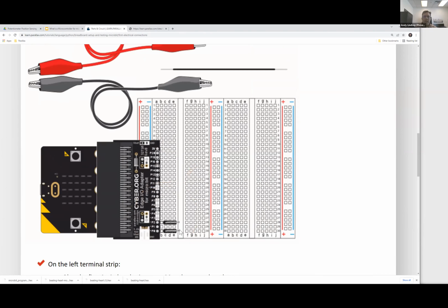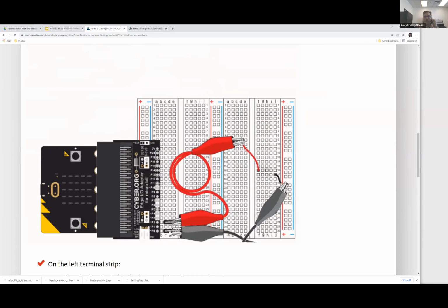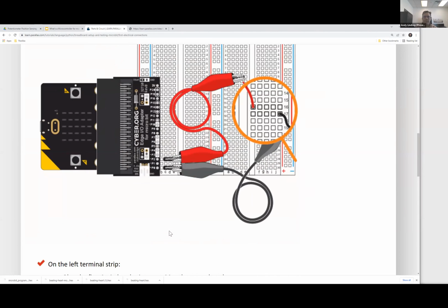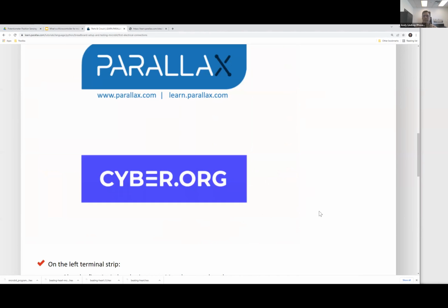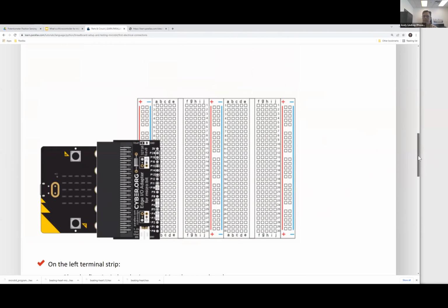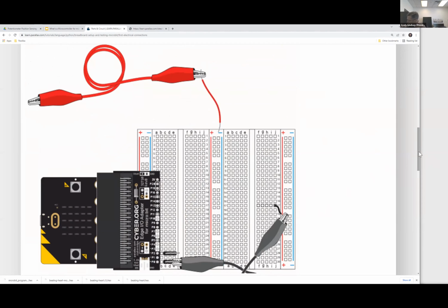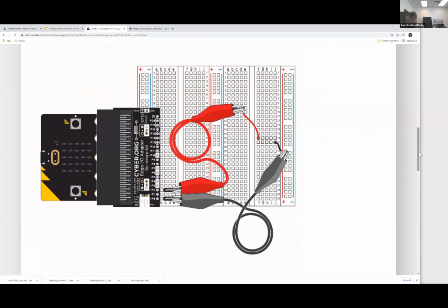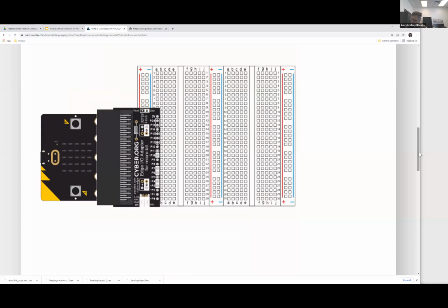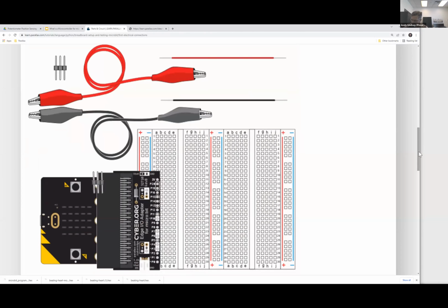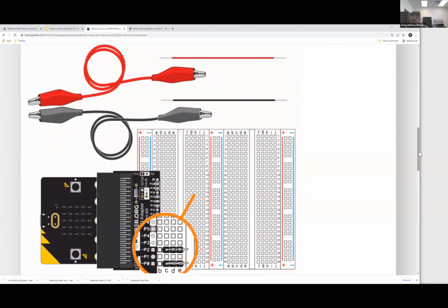So get as much alligator clip onto those headers and gripping those 3 pins as you can when you connect the alligator clips to the 3-pin headers. I'm hoping that the best way to pace myself is to do this along with you all.